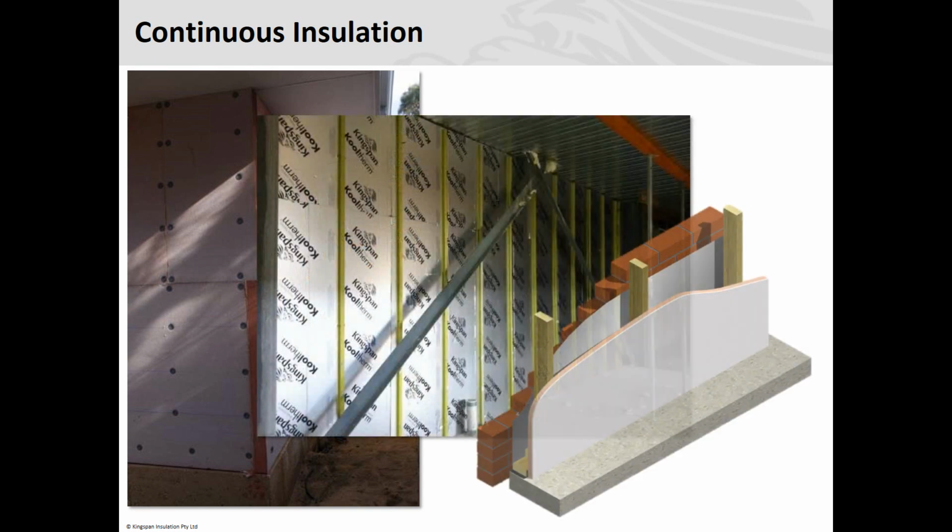Has insulation got a lifespan? Does it wear out? Well, it depends on what type of insulation you're talking about. Our Cool Therm, for example, we actually warranty the inherent R value for 20 years. With bulk insulation, like up in your roof, there's a lot of dust that settles in there. If you get a lot of dust settling in here, then the insulation becomes ineffective. So yes, insulation does have a lifespan, and inside a lot of roof cavities, in most cases it needs to be taken out, vacuumed, and then new insulation put back in.